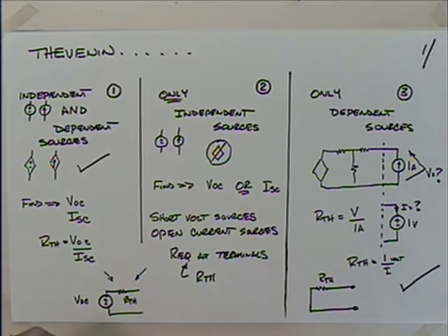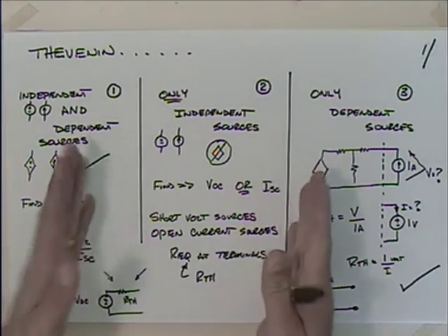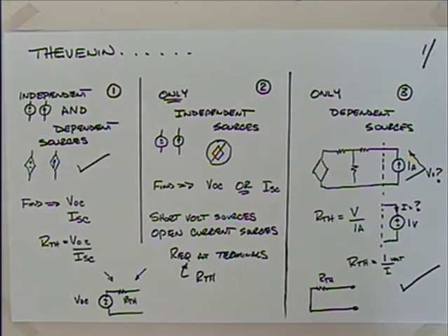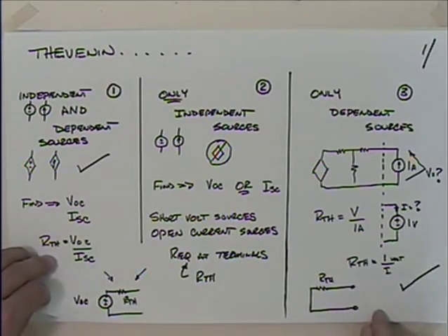Now, the other thing to think about is some people will use Thevenin's theorem for circuit simplification, and they'll look at building the Thevenin models to reduce the circuit. I haven't gone into that. I've used it more for a model so that we can figure out maximum power and things like that. But if someone uses Thevenin's theorem as a circuit simplification technique, that's fine. That's fairly standard too.